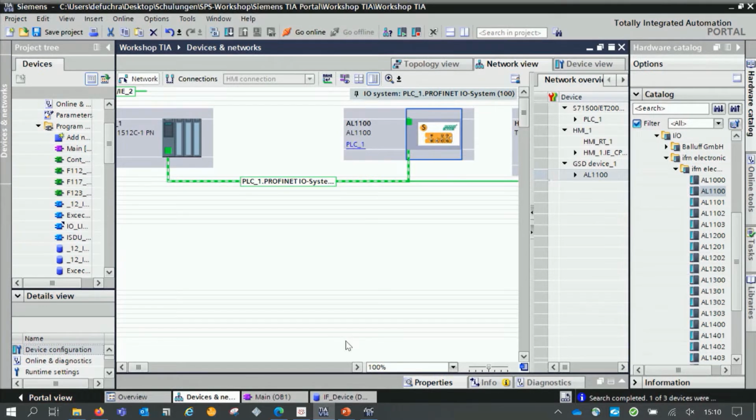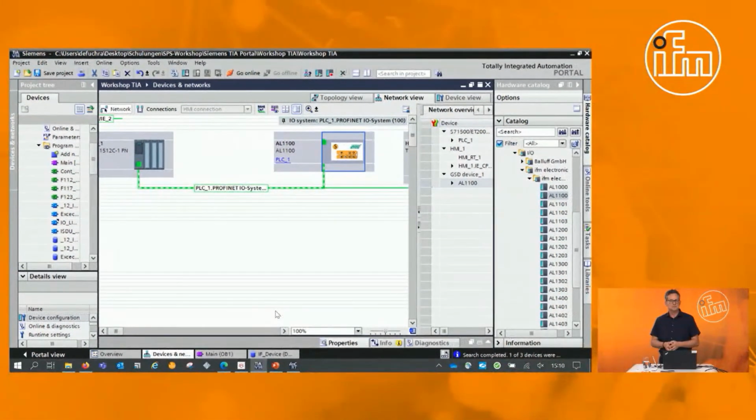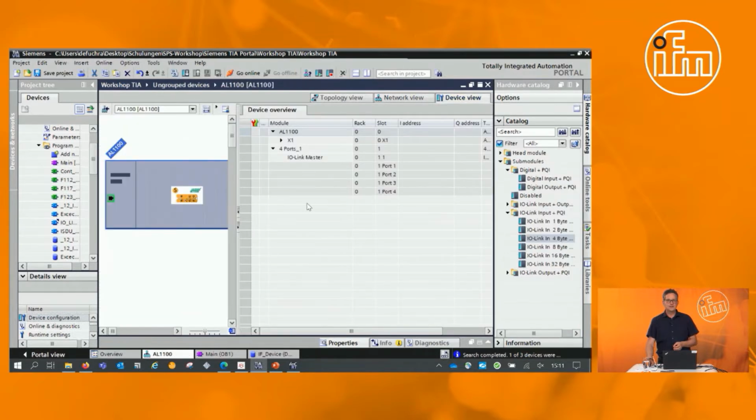I think for everybody who worked with Profinet, this is nothing new. It's the same story if you're connecting an IO-Link master or a frequency converter. So let's move to the IO-Link part. As you can see, this IO-Link master has 4 plugs, and the slots for them are empty. You have to configure here in your PLC surrounding how the different plugs should work.